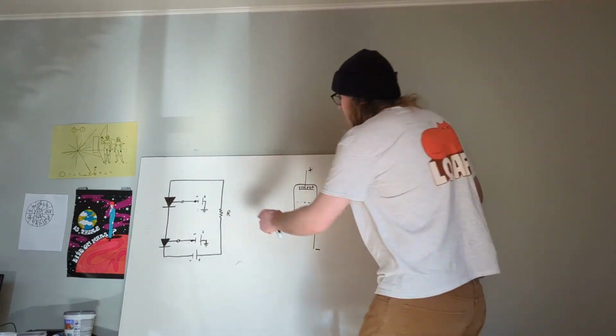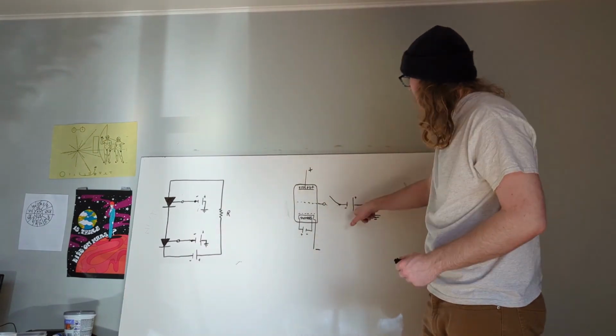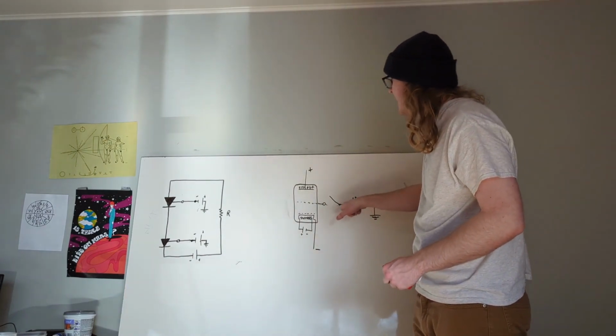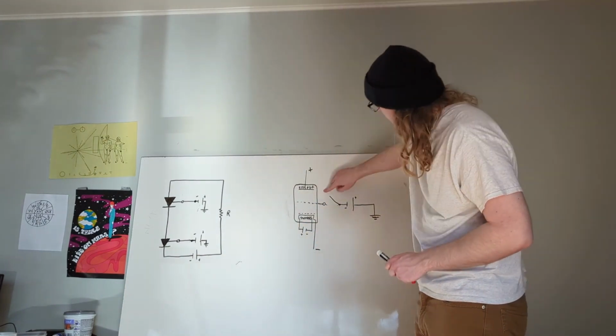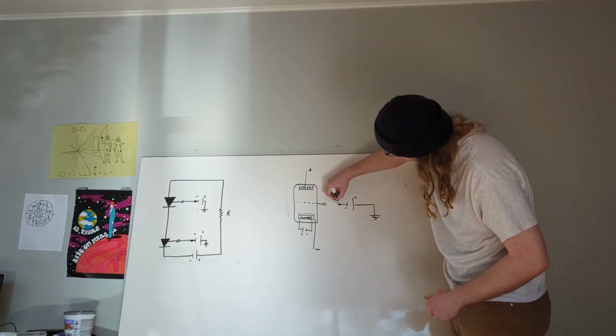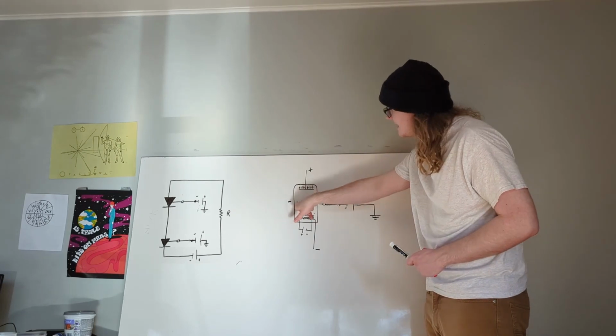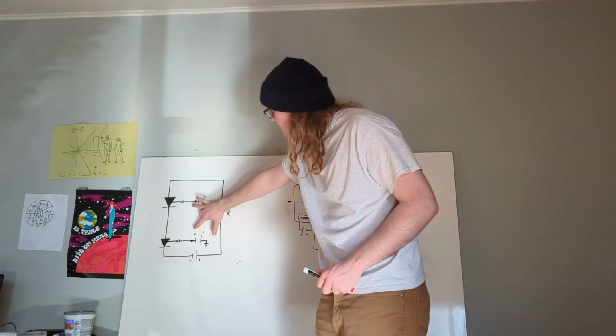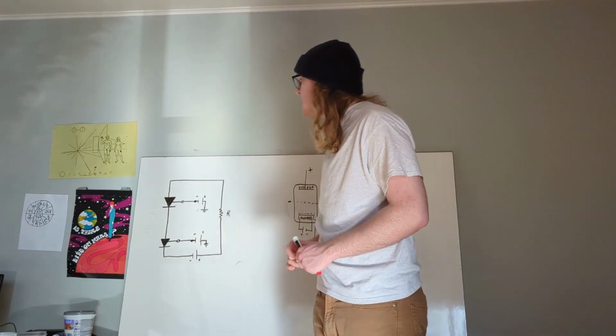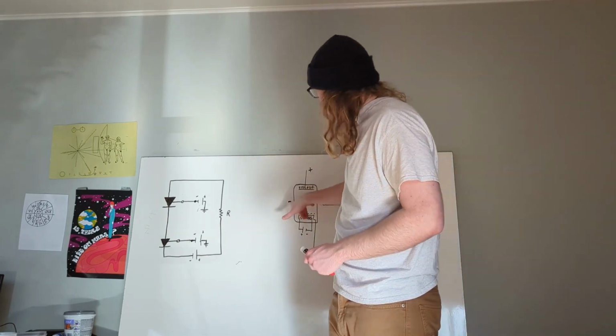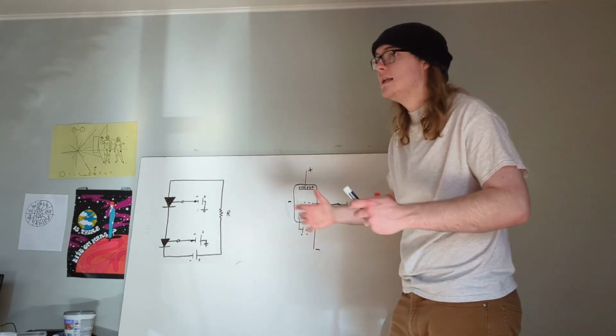Notice that in each of these configurations there's a ground source connected to the positive side of the battery and then the negative going into our grid. Notice that when this switch is closed, a negative voltage difference, or collection of negative charges, now exists across our grid. So when both of these switches are closed for each of these vacuum tube triodes, the voltage difference on the grid in each is a negative voltage.